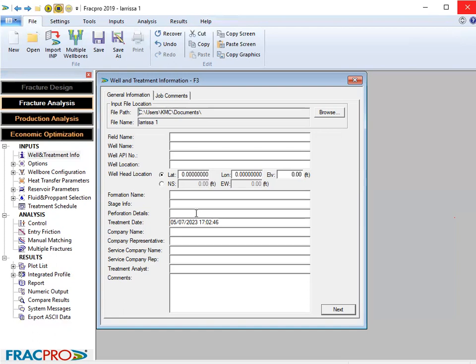I think we did hydraulic fracture wells in Prosper. I did that because I know that some students, at your final level of the BSc, may want to use this software for your research. If you're using the software, after you have done all of this analysis, you have to use the data, go back to Prosper and generate the IPR of that well, to show that after the hydraulic fracturing, the well is now producing at a higher level.